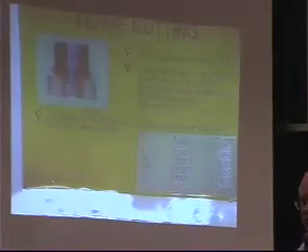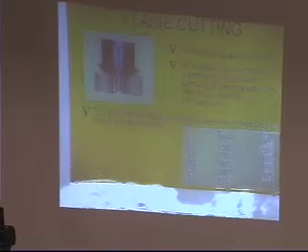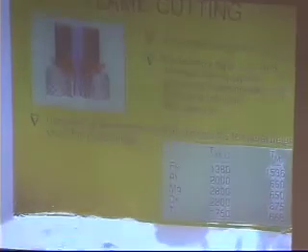So we eliminate the boundary layer, and remember the boundary layer is formed by these. In oxy-acetylene cutting, you have the oxy-fuel gas, which is converted to carbon monoxide, carbon dioxide, and water vapor. It hits a surface, and forms a boundary layer of these non-reactive gases on the surface. But in oxygen cutting, you heat up the sides, and then you blow oxygen straight through.